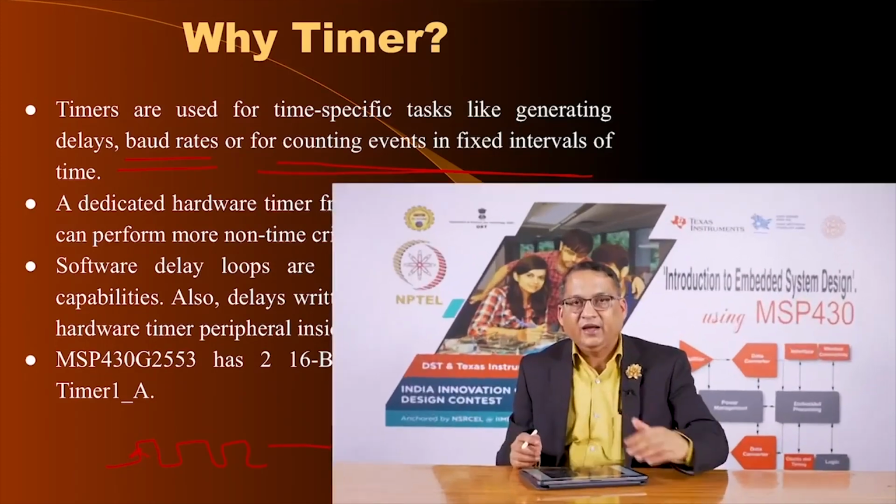But if you did that, your entire CPU life is going to be spent only counting pulses. You will not be able to do any other activity at the same time. By offloading this counting business to a counter, your CPU can perform other functions and keep on finding out from the counter how many events have happened. This is what the infrastructure related to a counter and a timer on a microcontroller usually allows you to do, and MSP430 is no exception.